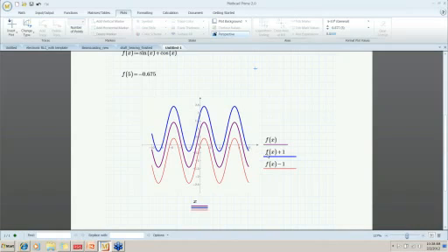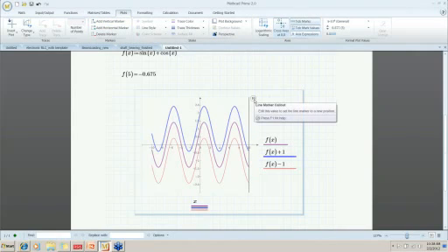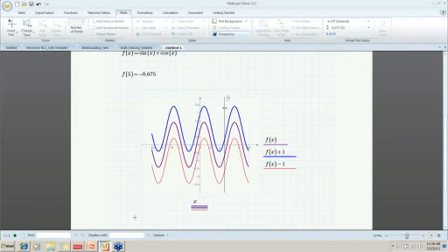Now, if we want to add some markers to the plot, we're going to click on Add Vertical Marker or Add Horizontal Marker. Okay, so if we put a vertical marker there, it puts in a placeholder where you want to put a marker for a specific data point. So if we want to mark a data point at x equal to 5, I'm going to put a 5 into that box. And then automatically we get this vertical marker going here down where x is equal to 5.